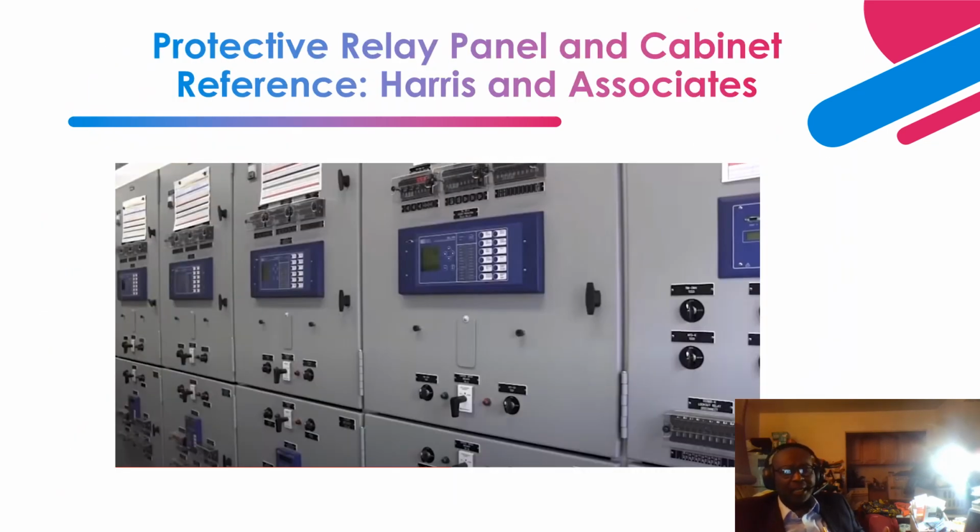Next, like I indicated, you can have a whole lineup of relay cabinets and panels, right? So this is a typical protective relay, microprocessor relay, right? Protective relays have evolved for years. They started from electromechanical relays, and believe me, there are a whole lot of electromechanical relays that are still in excellent working condition and very reliable. The only problem is every now and then they have to be maintained, like every 5 to 6 years, because they drift a little bit.